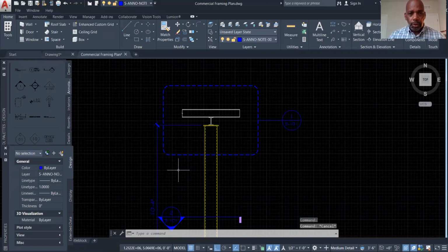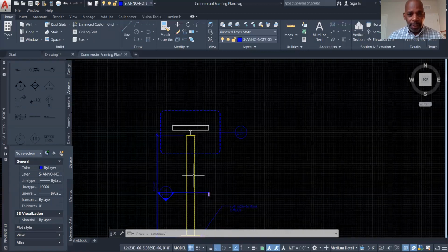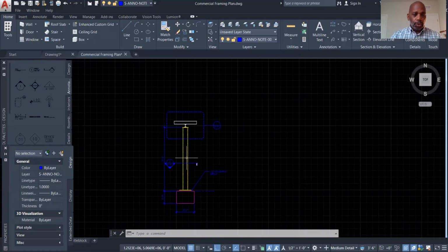All right. And typically these detail boundaries are thicker lines so they're more visible. All right, so with that, I've given you most of what you need to do to go ahead and annotate section A. Section B is going to be simpler in terms of annotation, except that it's not going to have a reference to the detail here, but all the other annotations should be similar, making sure that your annotation scale is 1/2 of an inch equals 1 foot.